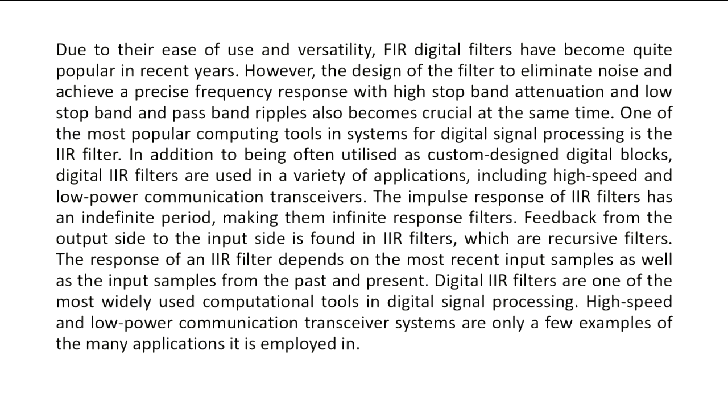Next, due to their ease of use and versatility, FIR digital filters have become quite popular in recent years. However, the design of the filter to eliminate noise and achieve a precise frequency response with high stop band attenuation and low stop band and pass band ripples also becomes crucial at the same time. One of the most popular computing tools in digital signal processing systems is the IIR filter. In addition to being often utilized as custom design digital blocks, digital IIR filters are used in a variety of applications, including high-speed and low-power communication transceivers.